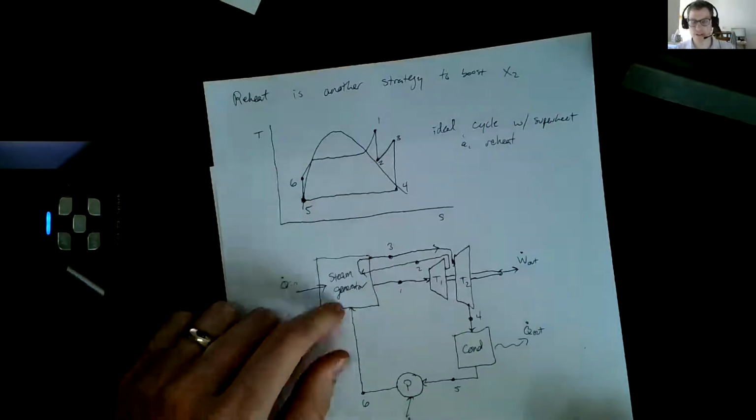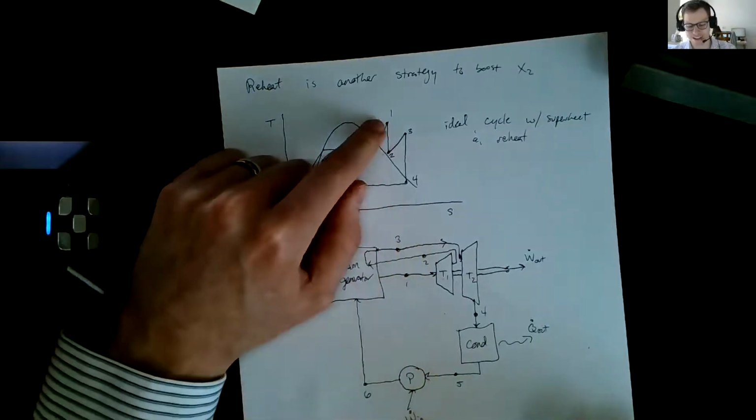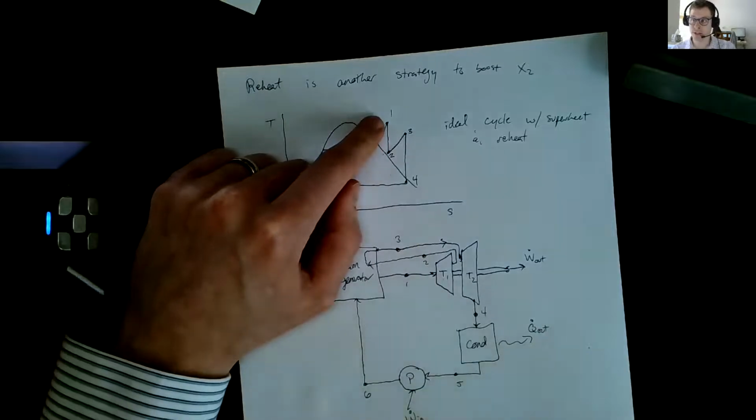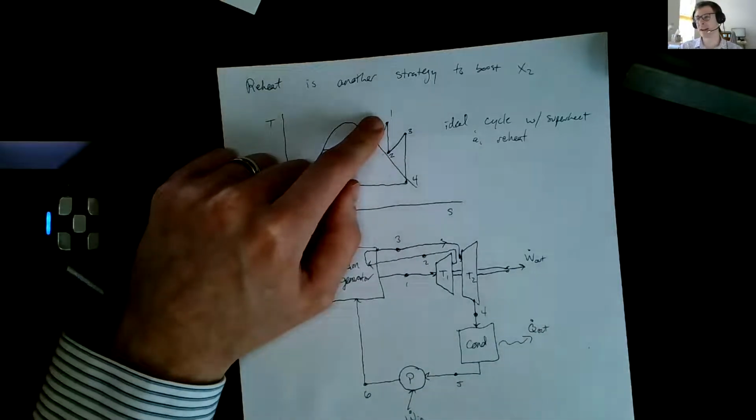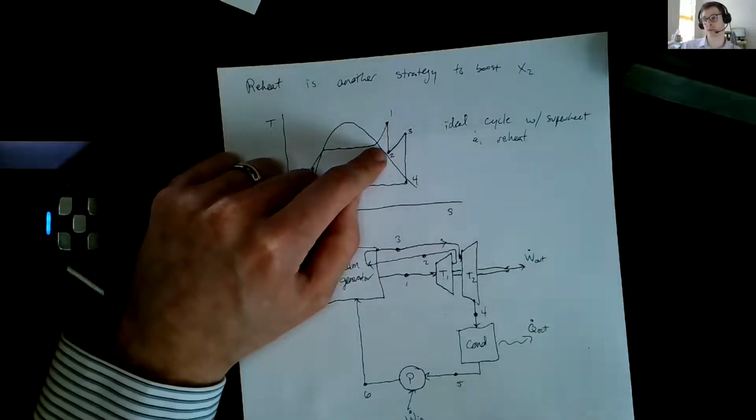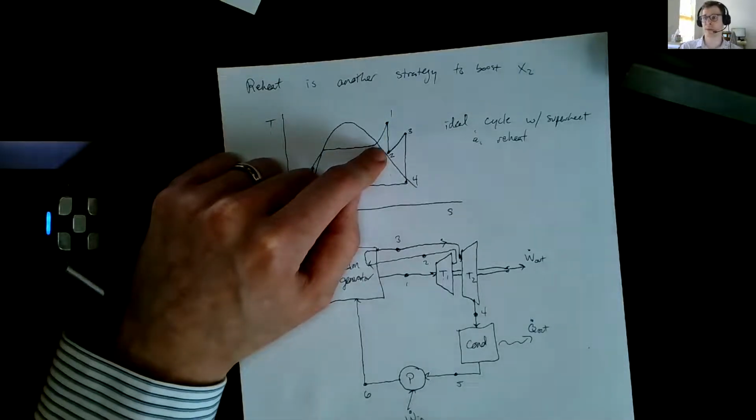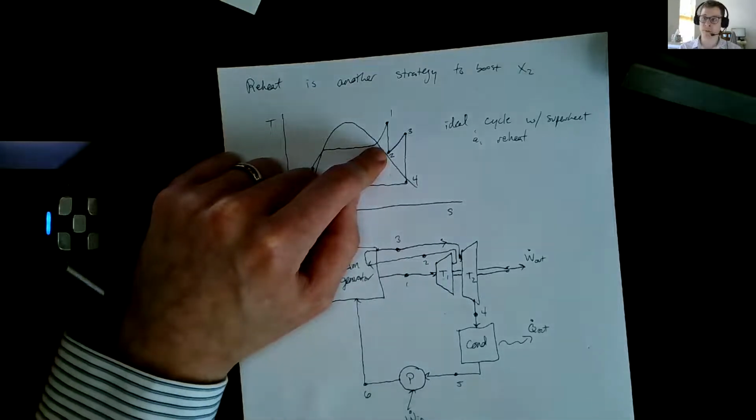What am I doing here? This is entropy. Because we have an ideal turbine. If you had a non-isentropic turbine, you would still follow the same procedure. You'd find state 2s, which is the virtual state at constant entropy, and then use your efficiency to find the real state 2. But in this case, we don't need to do that.